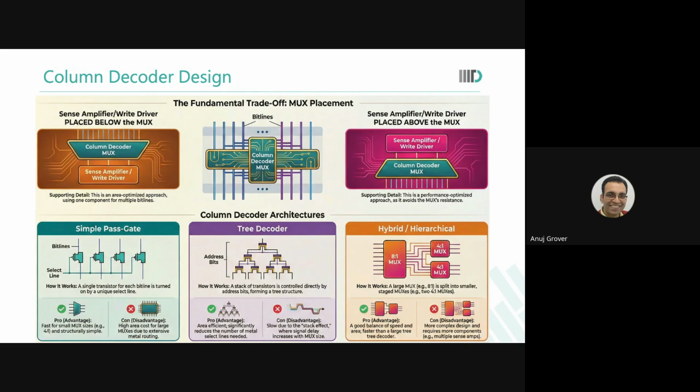Okay. So thank you. She's saying that in one of the earlier classes when I had talked about it, I said to remind me about ROM precharge, that I will talk separately about ROM precharge. See, until now when we're talking about SRAM precharge, we said that this is a part of the reset cycle.